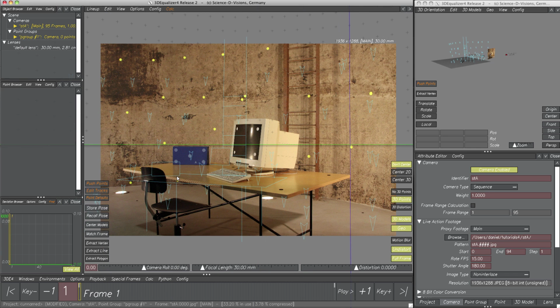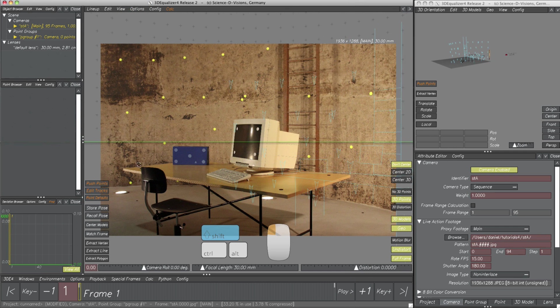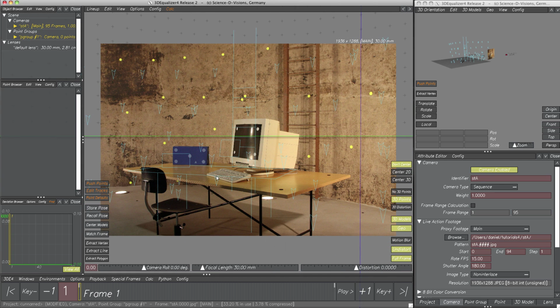A second mode how to rotate can be set in Options, Rotate Camera. After selecting Nodal, the camera will rotate around its own position. For this course, the previous mode is more suitable, so let's change it back to around target point. Before we start lining up the camera, we need some tiny preparations. The image plane is a bit disturbing in front of the 3D model. Let's scale the camera object to move the plane behind the model for a better view on it.